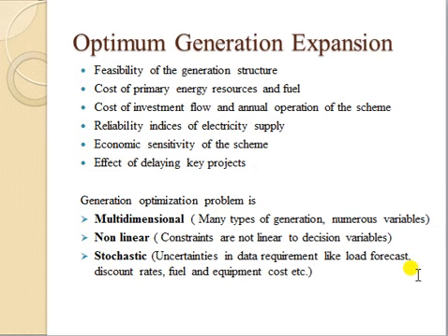So they always give you some different reliability standards like SAIFI, SAIDI, KAIDI. For generation systems you have LOLP, LOLE, those indices. Those you have to consider. Another thing is you have to understand the economic sensitivity of the scheme, whether after completion of this project it is going to impact my cost of fuel or cost of electricity generation. That you have to check.